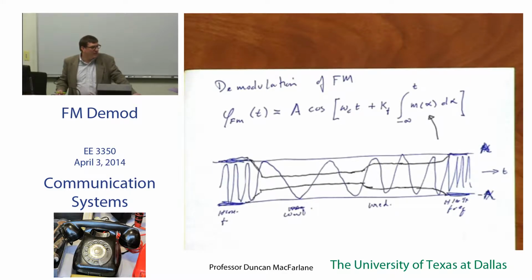And so, is there a way that I can force the final A to be a constant? You've probably done this by mistake up in the lab. I guess if you know what the attenuation on the receiver is going to be. You don't. You don't know what the fading is going to be. You don't know what the variation in A of t is. You're just stuck with a capital A of t coming in. What if you ran it through a limiter, like an op amp, an amplifier that had a gain on it, and it ran out of gain because of the low bias?